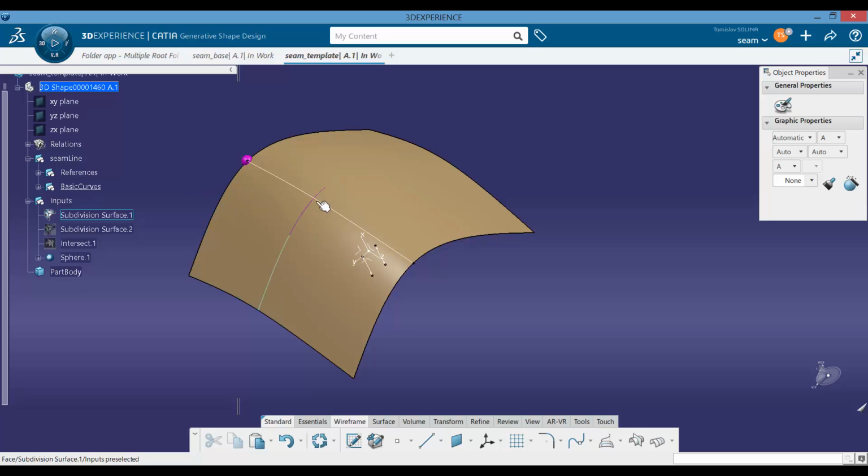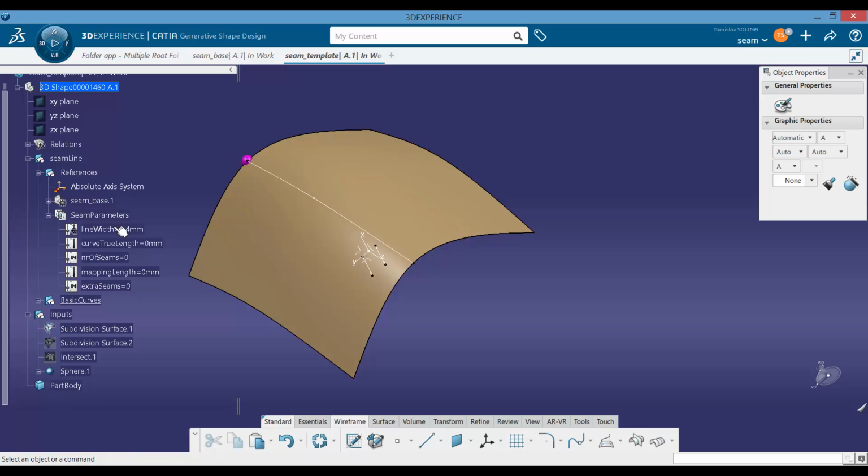And this can help us later, as we'll do a lot of parallel curves and operations with those elements, so that we want to keep things as simple as possible. And this gives us now the possibility to map this parameter, to define this length. So curve length, we can now do the measurement and apply it through the formula.